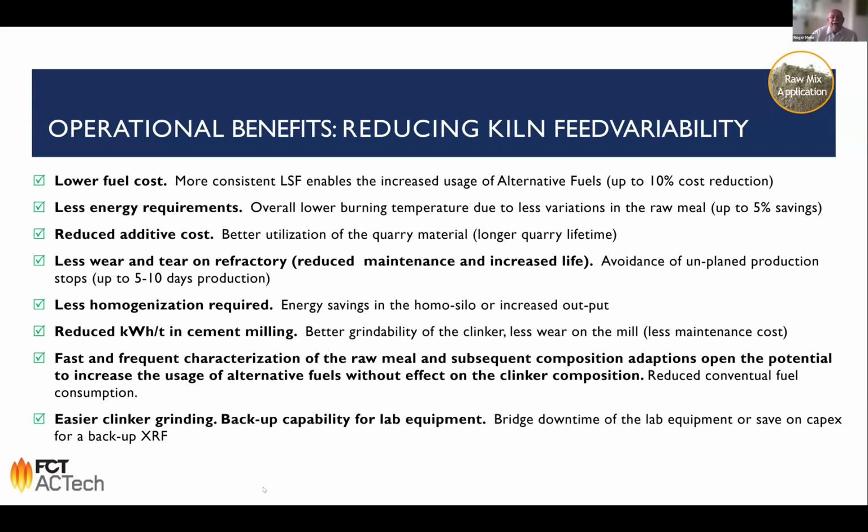Also, the frequent characterization of the materials gives you the possibility to really go to the limits of using alternative fuels. I only would like to bring into your mind that different fuels introduce a different amount of ashes into the process. So by knowing what the fuel mix is during the day, you can work more dynamically in the adaptations of the LSF.